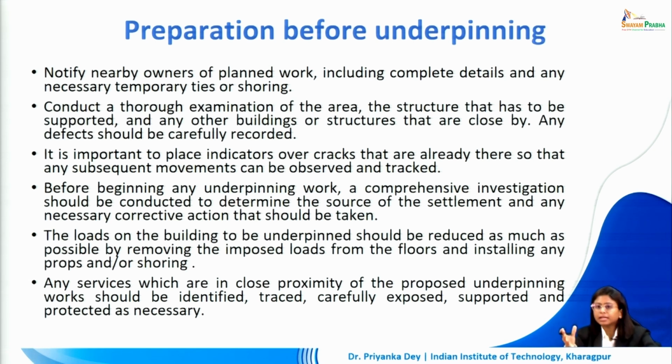So if we are at a position where there is a possibility of a wall to topple over, we would definitely want to give it some temporary support in the form of shoring before we start digging around in the foundation.